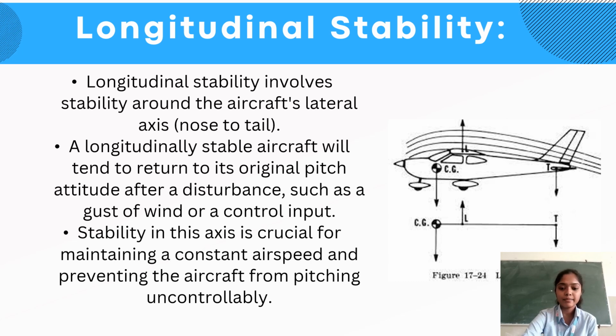The x-axis is labeled as angle of attack alpha, which is the angle between the oncoming airflow and the airplane's wing chord line. The y-axis is labeled as pitching moment coefficient. Pitching moment coefficient is a measure of the rotational forces acting around the airplane's pitch axis. A positive pitching moment coefficient means the nose wants to pitch up, and a negative pitching moment coefficient means the nose wants to pitch down.